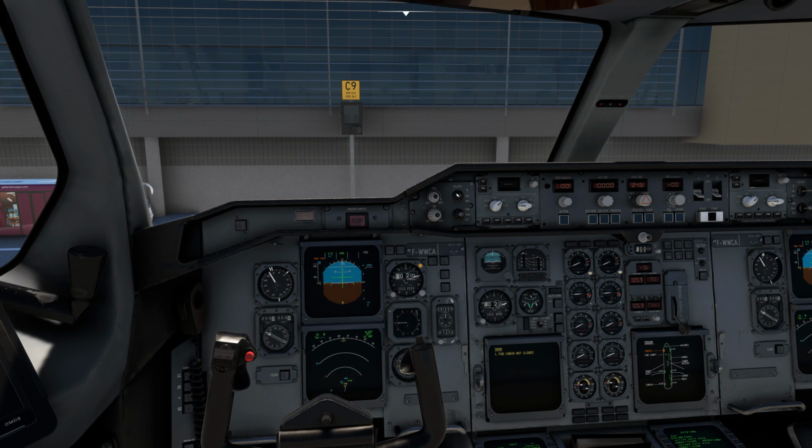Then over here, just make sure the flight director / FPV is on. The switch is in the on position. You will see this crossbar. If I turn it off, you can see it disappearing, but the flight director should be on for the autopilot and obviously for the ILS approach.